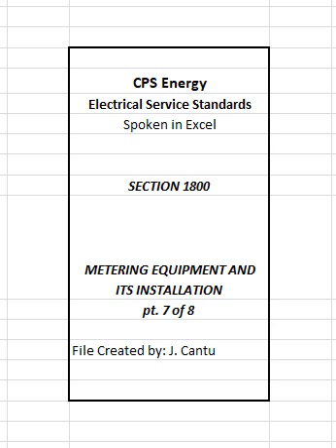1809 1. Installation of conduit or bus duct in CPS Energy equipment. Penetrations in CPS Energy metering enclosures for installing conduits or bus ducts shall be neatly drilled or punched and dressed smoothly. Penetrations shall not be burned. Conductor sizes number 4 AWG and larger shall be protected by insulated bushings or other substantial insulating material in accordance with the NEC. All unused openings in enclosures, sockets, gutters, etc. shall be closed using devices not externally removable.